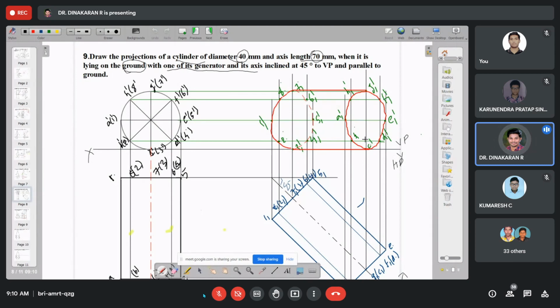If we fold a paper in a circular manner, no edge will form. In a pentagon, pyramid and so on, the longer edge or slant edge should be there, and that edge will be visible or invisible. But here we created the inside lines only for construction and projection purposes, so there is no need to draw thick lines inside; only the outside generators we show with thick lines.